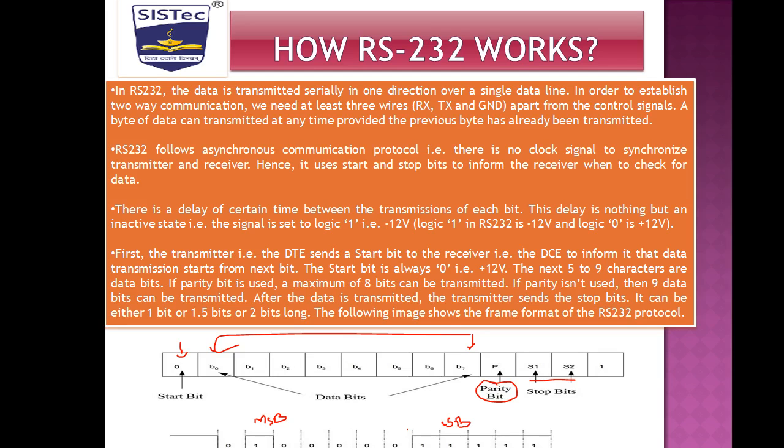After receiving DTR, the DTE requests use of the data channel by asserting the RTS signal to start the transmission. The modem at the receiving end is then dialed.